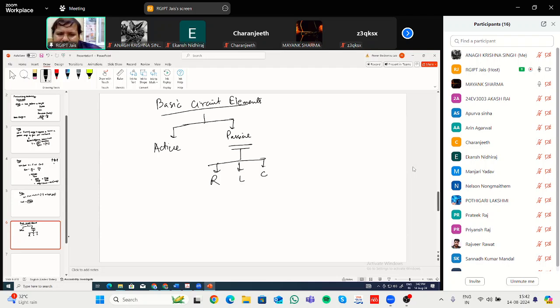So what is the resistance of a particular material? That depends on many things. It depends on the specific material, its internal structure like resistivity. It may depend on the length and the cross-sectional area of the material. It depends on the temperature T. Sorry, not time T. It is temperature T, or let us write it as T degree centigrade. So resistivity, length, cross-sectional area and temperature: based on all these things, you will get a particular resistance.